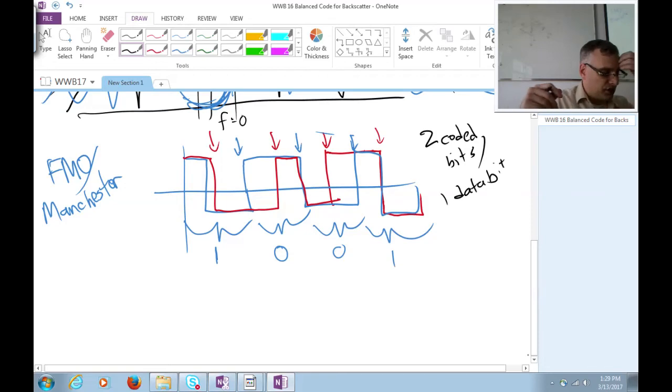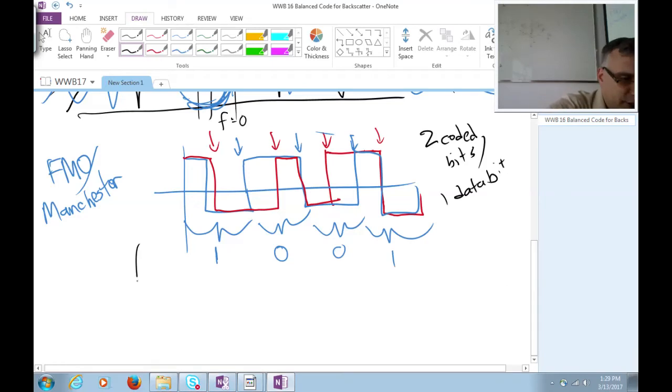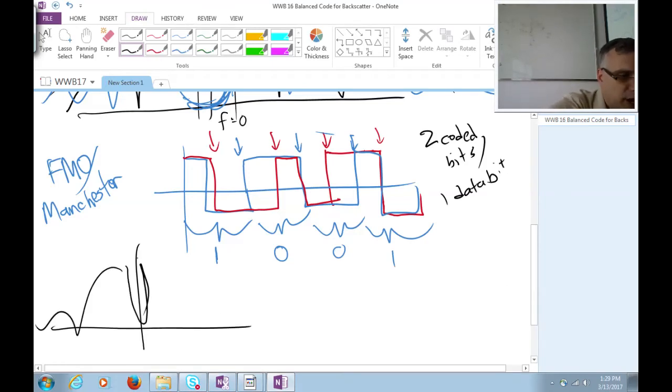And then this begs the question, well, can I go any further? Can I reduce it further? If you look at information theory, all we're actually trying to do is get rid of the DC component around what is otherwise a sinc squared type power spectral density.